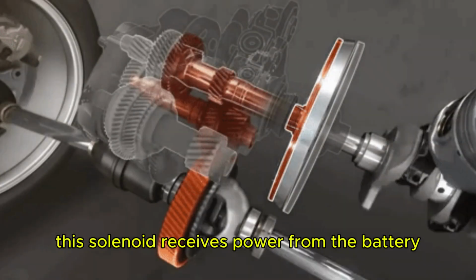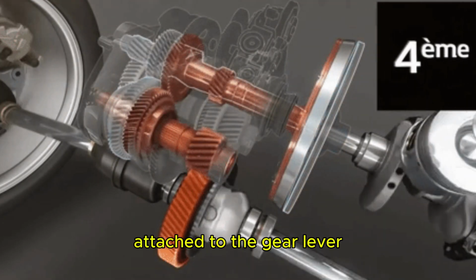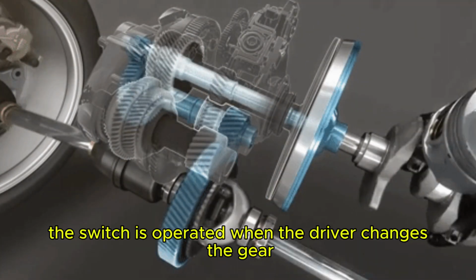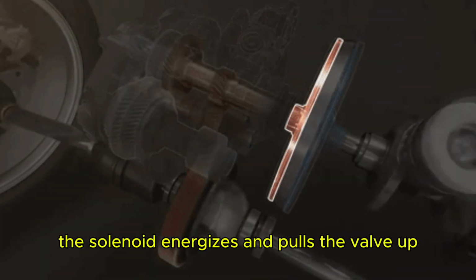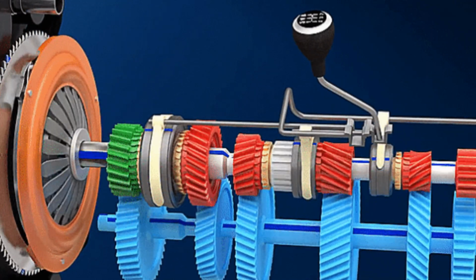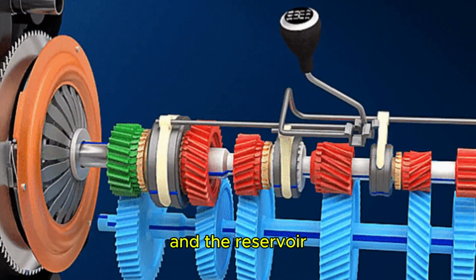This solenoid receives power from the battery for its work, and the circuit has a switch that is attached to the gear lever. The switch is operated when the driver changes the gear by holding the gear lever. The solenoid energizes and pulls the valve up, which connects one side of the vacuum cylinder to the reservoir. This mechanism opens the passage between the vacuum and the reservoir.